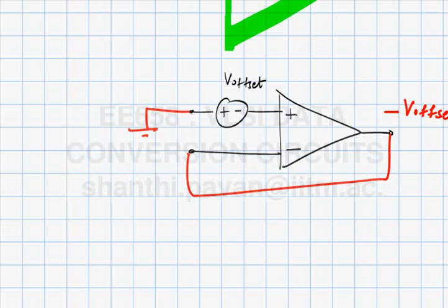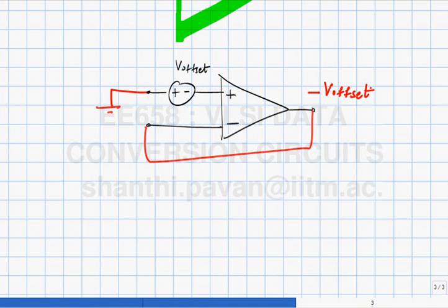But okay, the basic idea is the following, right? You have this knob. What will you do? I gave you this box with 2 inputs and 1 output, right? And I told you the input-output offset is from V offset. So what will you do in the lab? As he said, put a knob, put a differential voltage between the 2 inputs and go on varying the voltage, okay, and see where the output goes to 0. So this is nothing but a negative feedback loop, right? If the output is not 0, I will keep changing the voltage in the proper direction until the output eventually becomes 0.